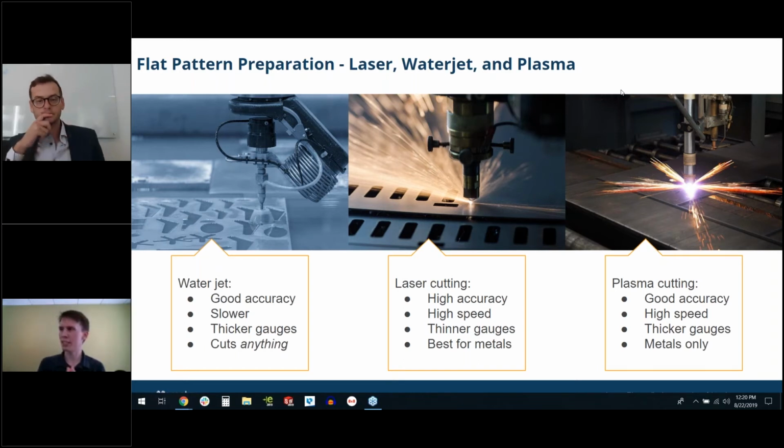Yeah. Now just talk about edges real quick. So I know water jet tends to have a slight taper on the edge curve, and that's because you're shooting essentially abrasive water flow through, and it has almost a slight curve out pattern. Laser, because of the gauges, you don't see that as much, or it looks a little bit cleaner. Yeah. Particularly in the fiber lasers now, because a CO2 laser, imagine cutting with a 0.01 end mill, right? And it distorts when it hits the material, and it can do certain materials better than others.